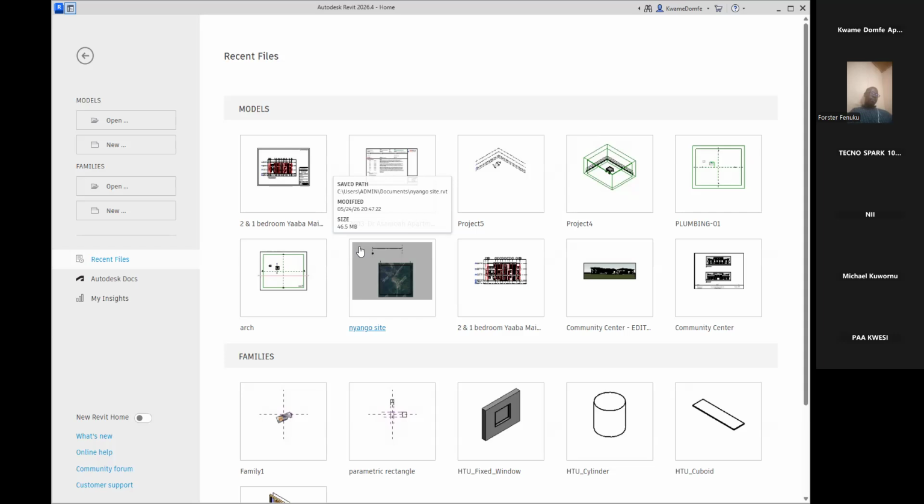People were using ways and means to scale their drawings. In AutoCAD, there was something we call layout. If you've used AutoCAD before, we have the model view, then we have the layout view. Ideally, if you are using it properly, you do all your work in the model view. Then when you want to set up sheets, you use the layout to create different sheets so that you can manage your views on those sheets.